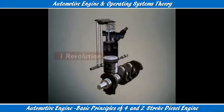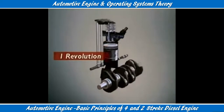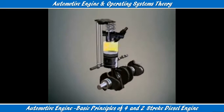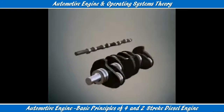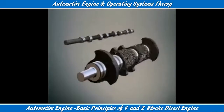So the cams must make just 1 revolution, and if the cams make 1 revolution, so must the camshaft. But in each 4-stroke cycle, the crankshaft rotates completely twice, so the camshaft must rotate at half the speed of the crankshaft. This can be achieved by gears.